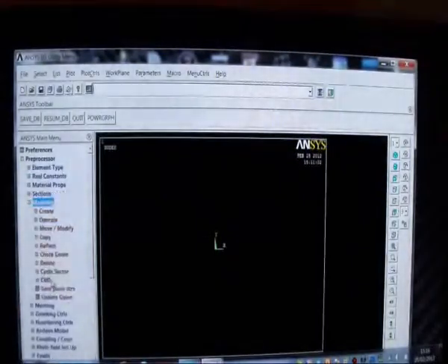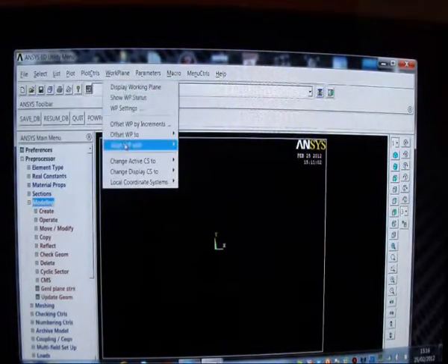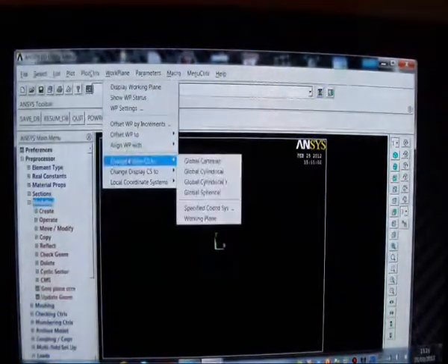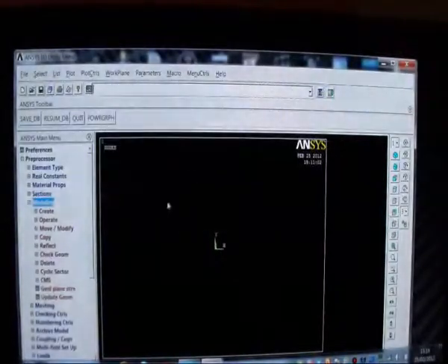So I'll pick that up there. Let's get out of this. We've got material. I exit that. I'm going to model it for sections. I've got to be careful now. I'm going to change my work plane from Cartesian to global cylindrical. I'll go like that because it's easy to put it in there.